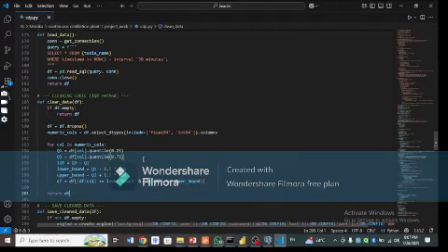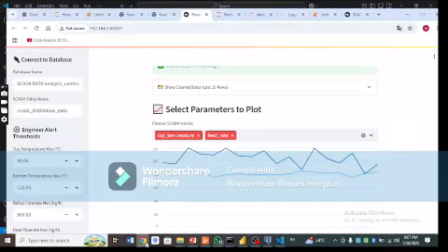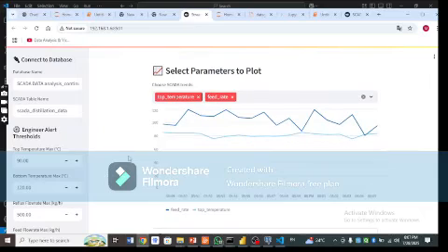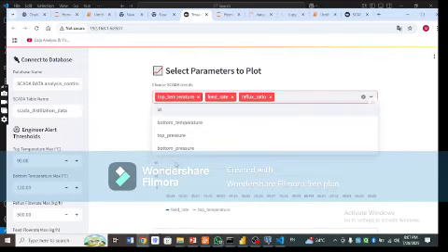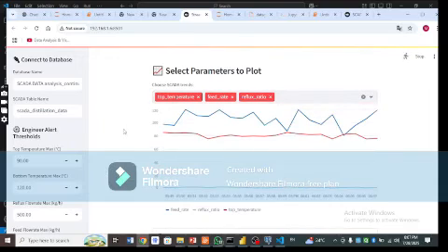Now, from a process safety point of view, most importantly, we don't disturb the real plant parameters. We are only working on the analysis layer without touching the actual running process. We have added a special feature in the dashboard. Plant engineers can set the threshold values. For example, condenser temperature must stay below 78 degrees Celsius. If any threshold is crossed, the dashboard instantly generates an alert.